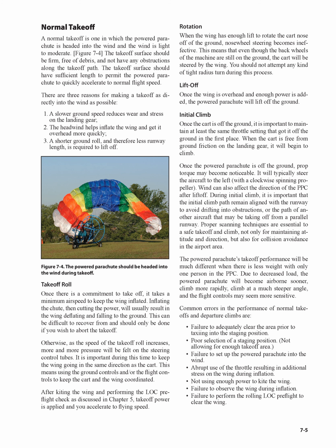The powered parachute's takeoff performance will be much different when there is less weight with only one person in the PPC. Due to decreased load, the powered parachute will become airborne sooner, climb more rapidly, climb at a much steeper angle, and the flight controls may seem more sensitive.